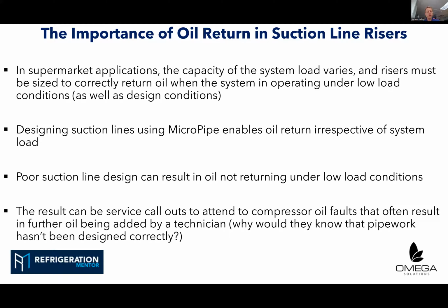Ultimately, you get too much oil in that system, and it's an oil problem. We're going to look at adjusting defrost settings. Eventually, we're going to get that oil back, and then all of a sudden, that technician realizes there's too much oil in the system. But it was never a consequence of that technician. It was a consequence of an inappropriately sized suction riser.